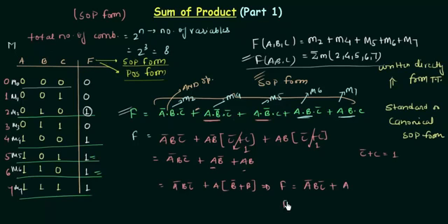If you remember the distributive law, if you have the case A or A complement B, just neglect A complement. In the same way, if I say B and C complement is X, then I have A or A complement X. I can neglect this A complement and I will have A or X. X is equal to BC complement, so A or BC complement.